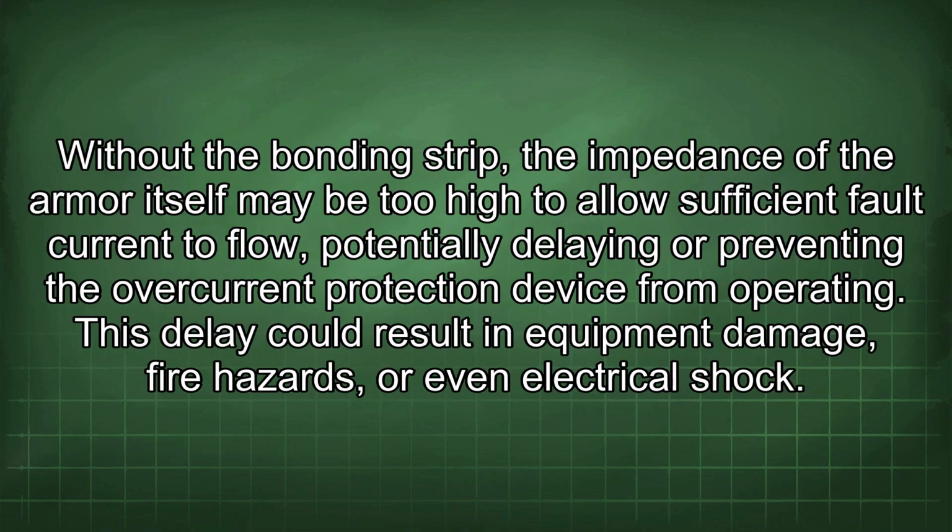Without the bonding strip, the impedance of the armor itself may be too high to allow sufficient fault current to flow, potentially delaying or preventing the overcurrent protection device from operating. This delay could result in equipment damage, fire hazards, or even electrical shock.